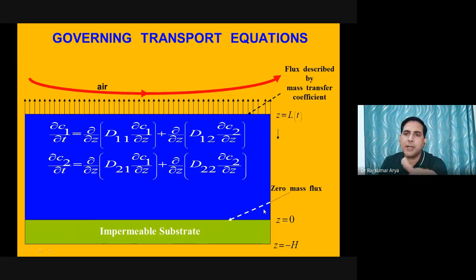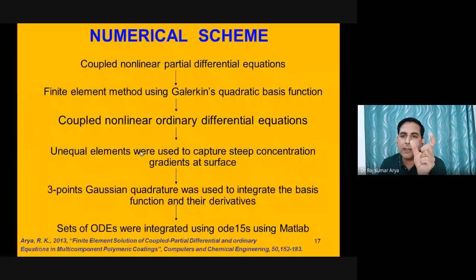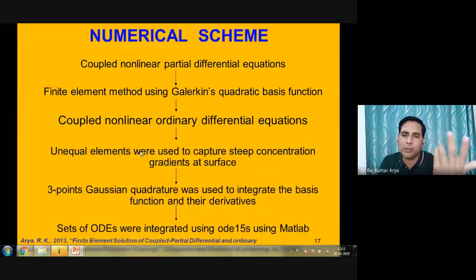On the bottom side I don't want that, because the variation there is not too much, so I want bigger particles, meaning bigger element size. Why would I do this? Because each element will give you several equations. If the number of elements is too high, you will unnecessarily get too many equations, and therefore your computational time will go up.